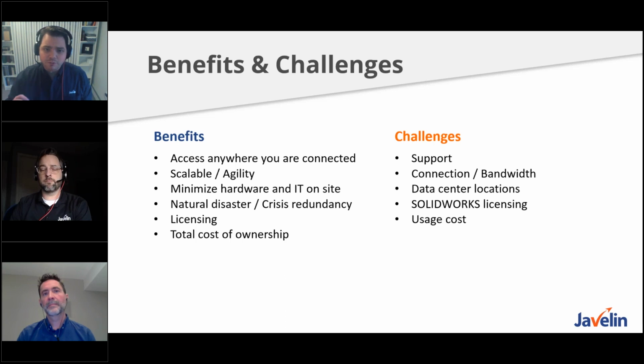And one other one that we've got there is regarding SOLIDWORKS licensing. That's a requirement that only network licenses can be used on a cloud installation. So the standalone license cannot be used in this environment. And the SolidNetwork License Manager that has to be used must be 2019 SP2 and newer. So very small requirement, that's an easy one to address. But the big thing to remember is it's the network licenses that can be used in these environments.